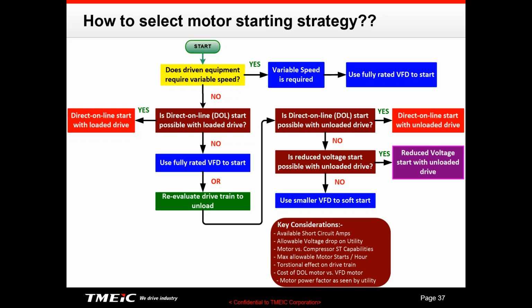Also, the VFD costs a lot of money compared to the motor, so you have to look at the cost comparison. And then what's the motor power factor as seen by utilities. So there are a lot of things you have to consider, but there's no yes or no answer here. You have to look at all the possibilities to select the proper starting method for the motors.